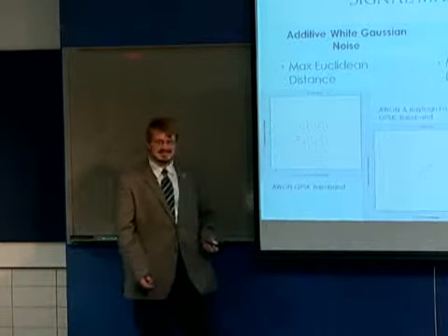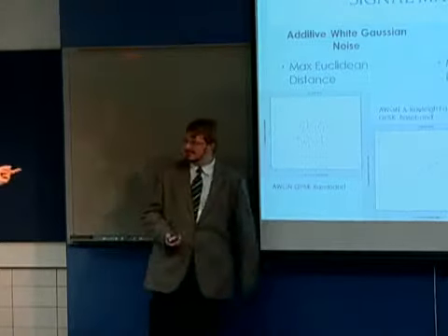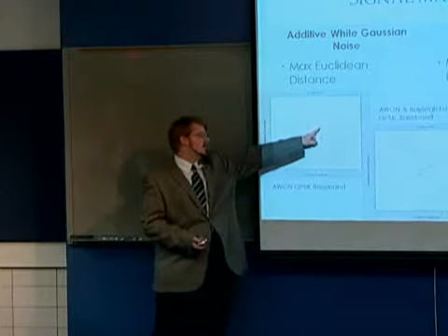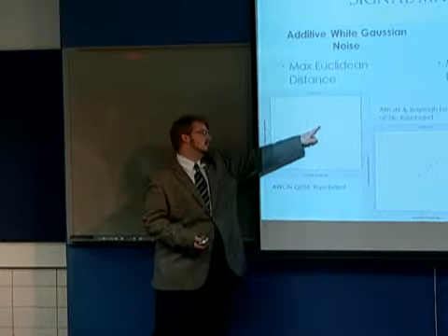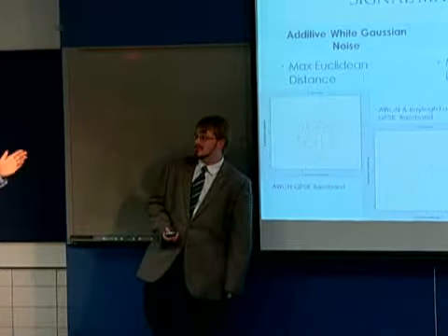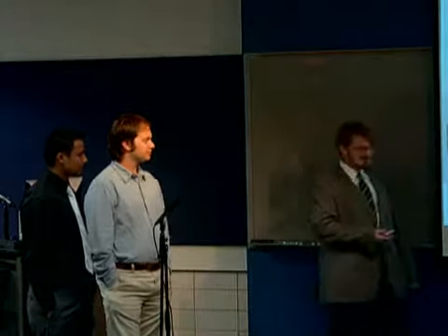Yeah, I think so. But it would be nice if you also highlight where the original signal constellation points are without noise. It's like negative root 2 and root 2, maybe square root 2, something like that. If you broke up the points post response into several quadrants and took the mean, because it's a Gaussian distribution, you would actually get the original point. But I think just for the sake of the audience, it would be nice to explain that. Okay.